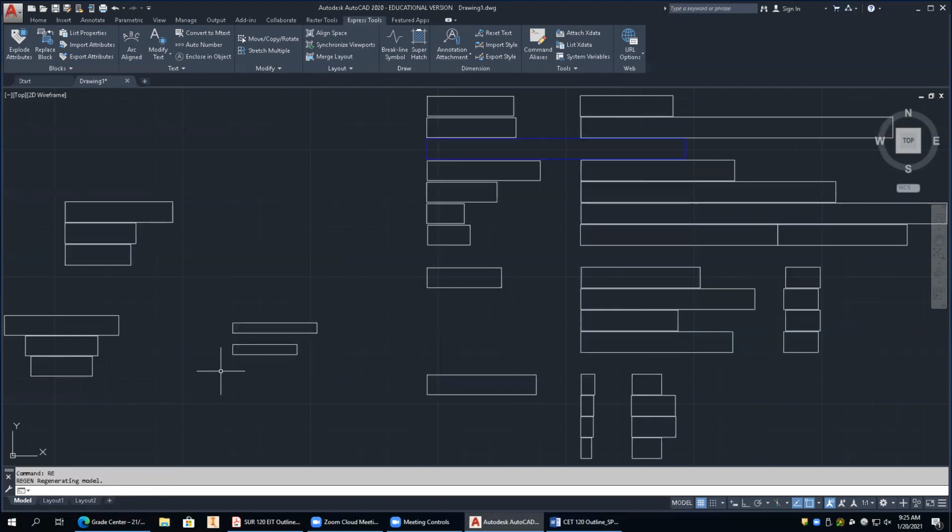What happened to your text? Whoa, where'd it go? It's QText. So what it's showing you is a placeholder for that text. That allows you to not have to deal with the text when you don't want to draw through it. So as I'm drawing other objects, it just saves that time.